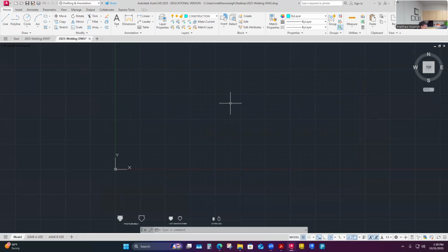It might have layer 0 with nothing on it, and then just the visible line layer. So it's going to simplify things. I'm going to be able to strip down a DWG file, or even just export a DXF file that's a stripped down type of file with just the machine cut lines that need to happen. That's what our machines like.